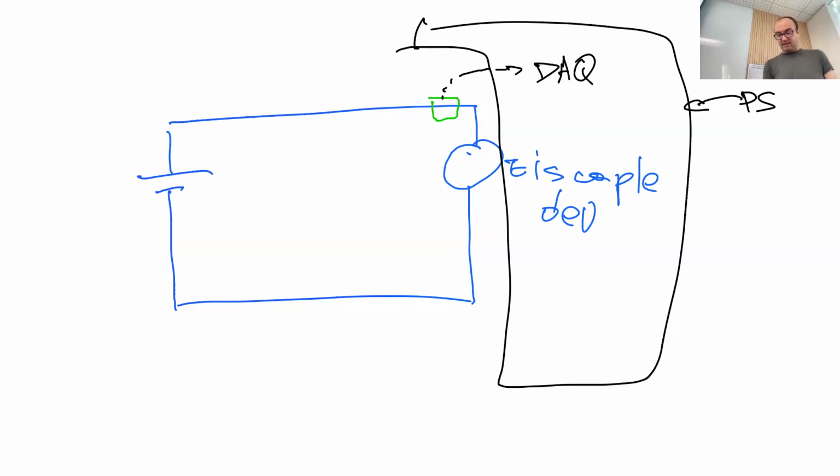And these cables are quite thick, like the ones that you already have in your fuel cells. It turns out that just a couple of meters, 1 to 2 meters of cabling, if we move this shunt here or here, adds 2 to 3 degrees of phase difference.